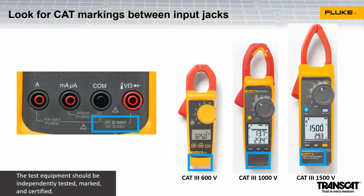Now, the size of these pictures is relatively indicative of the size difference of the actual meters themselves. As you go up in category and voltage, the creepage and clearance requirements internally to the device increase, to ensure that it's going to be safe and be able to withstand those transients. So the size of the tool goes up. You can see that the 393 is quite a bit bigger than the 325, but that's because it's designed and built for that higher voltage environment.